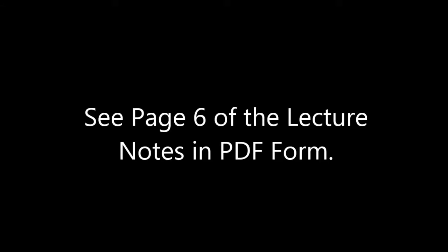Let's see, we were on page 5, so I'll say this is page 6. So this is from the American Institute of Steel Construction. They've got their steel design handbook. Those of you going to structural engineering, civil engineering next year will definitely have one of those. And that talks about different types of columns and the theoretical value for K. And then we realize that not everything is perfectly theoretical, so it talks about what your recommended value is.